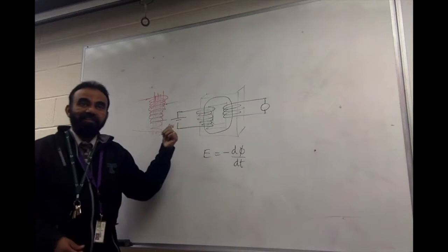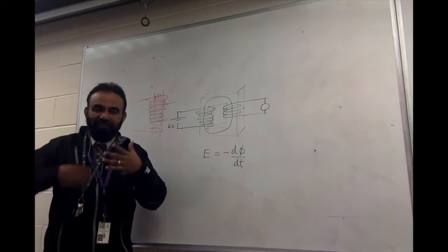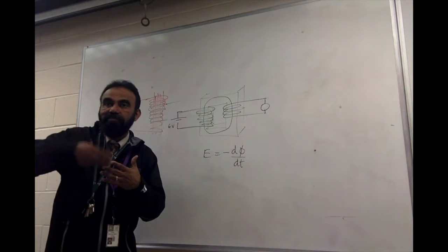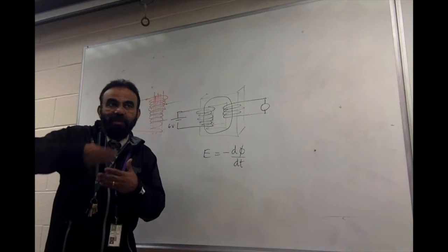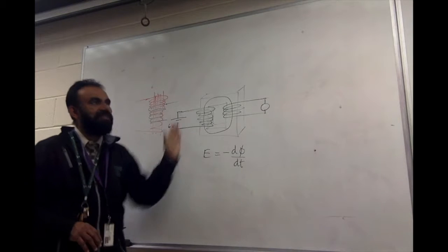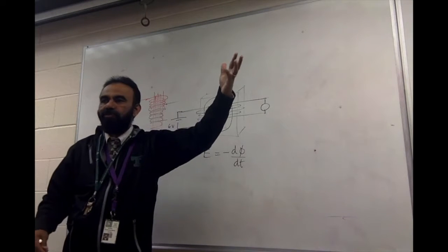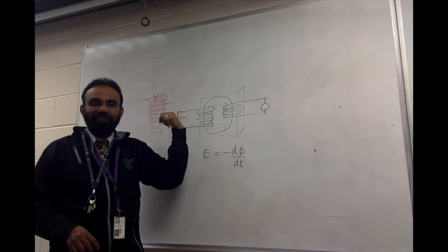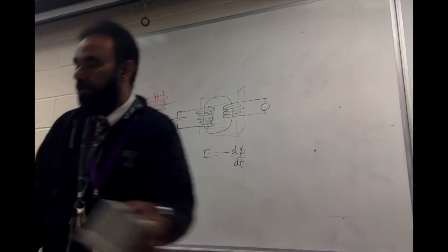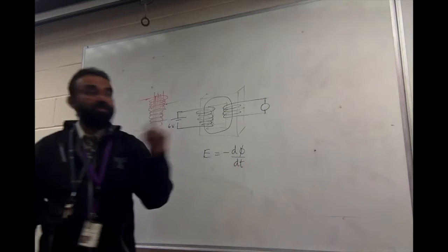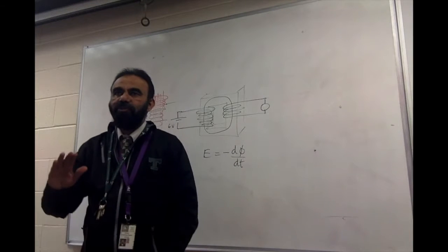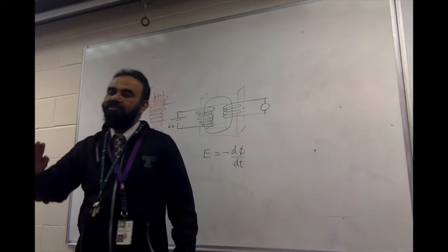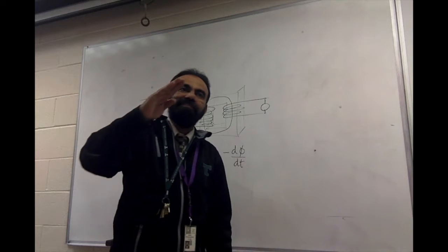When I connected it, the current here is kind of getting established. Make sense? It is not able to suddenly go to the highest value of 1 or 2 amperes. So there is definitely an opposition. And because of the opposition, the current here does not grow all of a sudden like that. Instead, it grows like this.